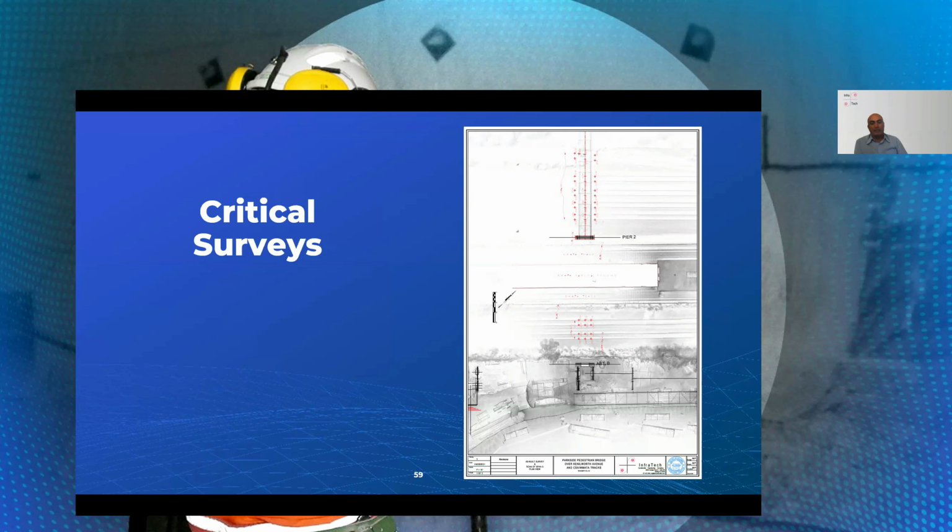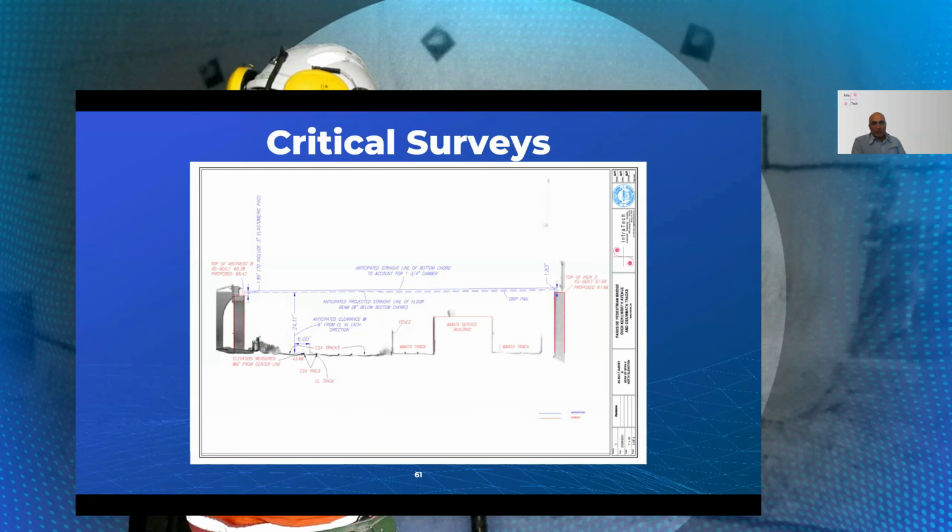This is the same situation. Before the bridge goes up, we need to confirm our clear height. We need to make sure that everything is as it was designed, and nothing has failed in this case. We see on the left side the piers and the abutments. On the right side, the same thing. Again, less intensity on the right side because I was far away, but still enough data to create this survey to see how the situation is.